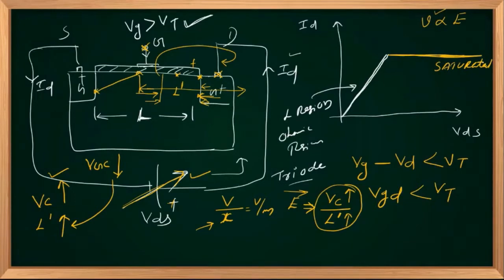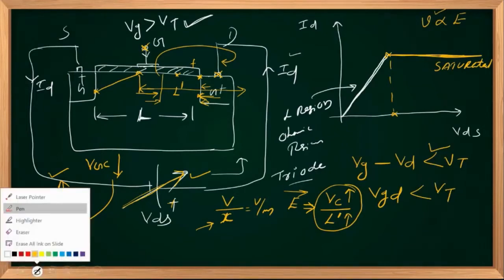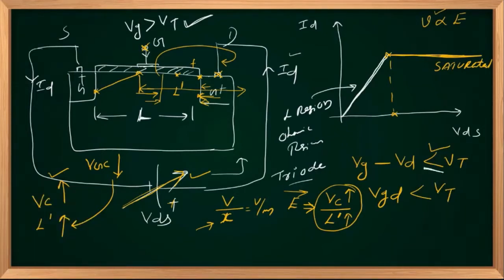And what is the condition for saturation? Gate potential minus channel potential at the drain end should be less than or equal to VT. Right? And the starting point of this flatness occurs at which point? It is true if Vg minus Vd is less than Vt, and it starts at a point Vg minus Vd, or Vgd, equal to a Vt value.